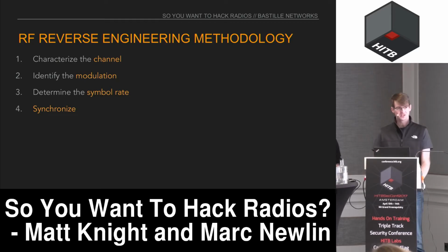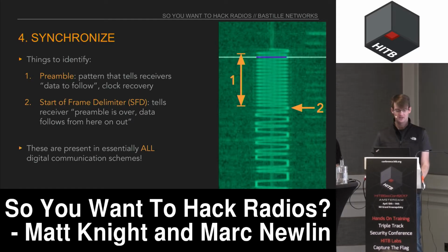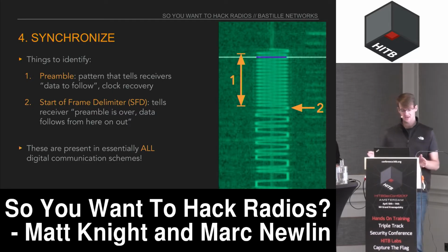Step 4 is to synchronize against our packet. So we're going to write some software that will essentially identify the preamble and the start of frame delimiter. And these are the two elements that we just talked about with that interactive example. They're present in just about every wireless digital communication scheme that's out there. Essentially, the preamble is a pattern that the transmitter sends out to tell the receiver that data is soon to follow. It also helps with clock recovery. We'll talk about that briefly later, but really the preamble just says, I'm about to send a packet.